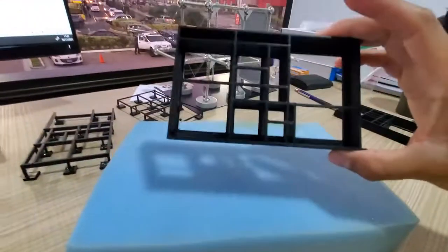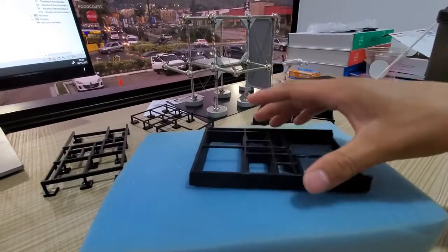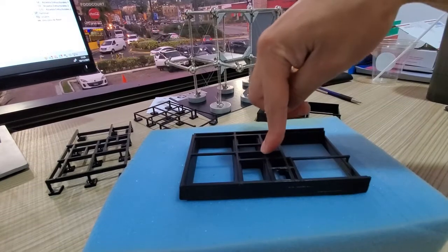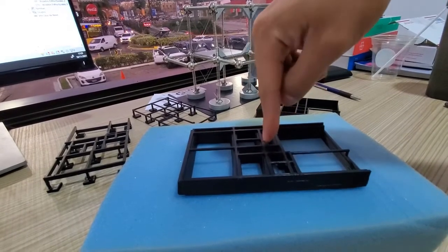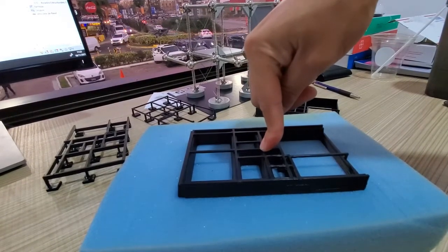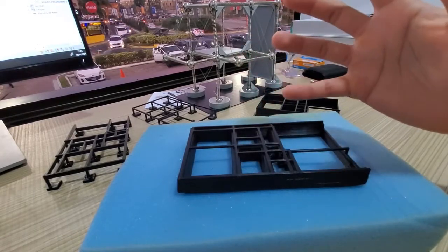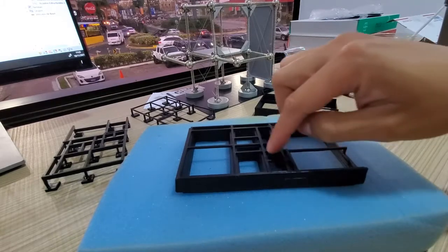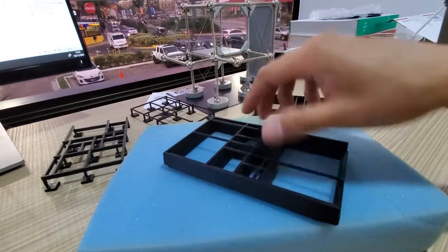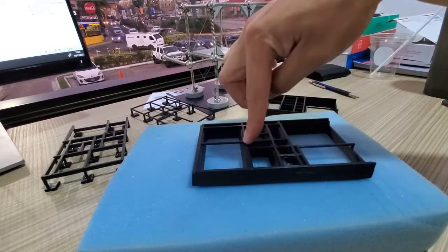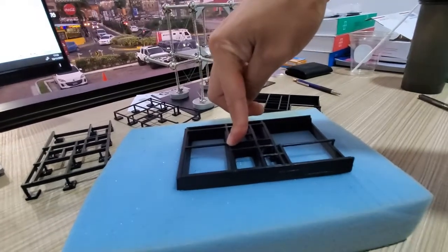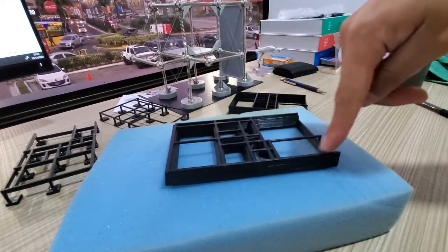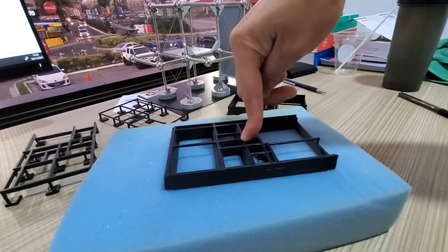And as with this one, the stiffness of this footing system is such that if a higher load is applied at some point, the system tries to distribute all the forces in all the neighboring footings. So we might expect no differential settlement with this kind of footing system, as you can see here.